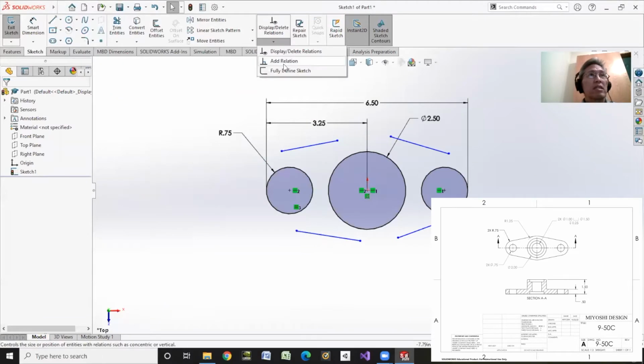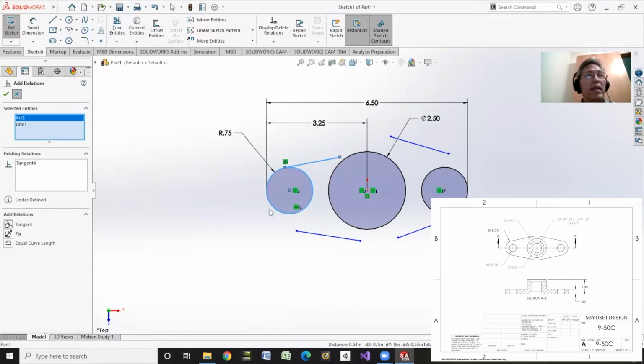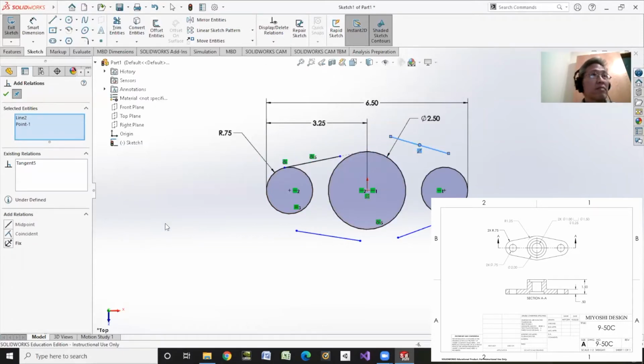Then we'll just add some relations. Line, circle, tangent, and if you grab the same circle, it actually deselects it, right? So I can either grab that guy and grab that circle to deselect one, then select the other one, make them tangent. Or I can grab a new object and an old object. Actually, I didn't want that center. Get rid of you. Like that.